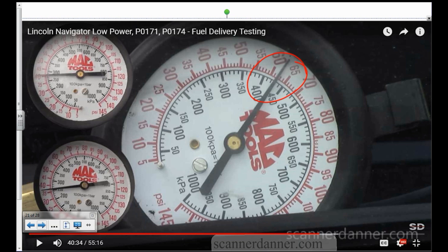systems. The regulator is in the tank. So when I snap the throttle and my pressure loss occurs up at the rail, there's a little bit longer response time for the regulator to account for that. It is normal on returnless systems, when the regulator's in the tank, to get a few psi drop in pressure on the initial snap throttle, just because it takes time for that regulator to account for a pressure change.